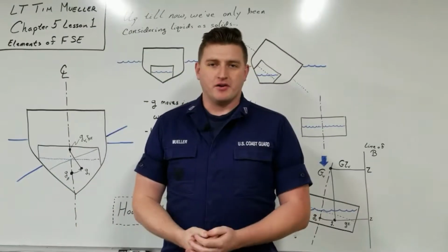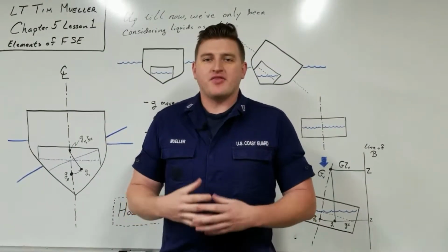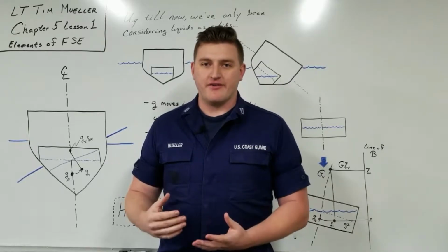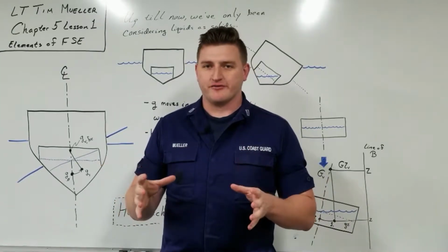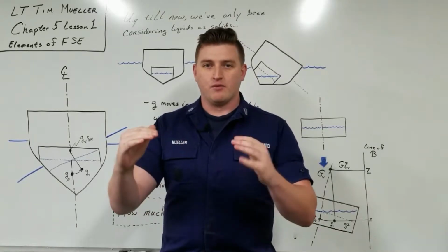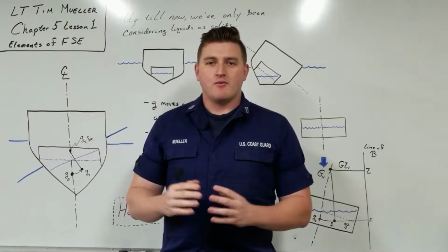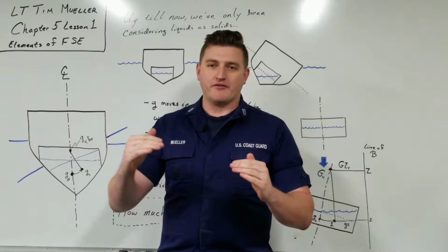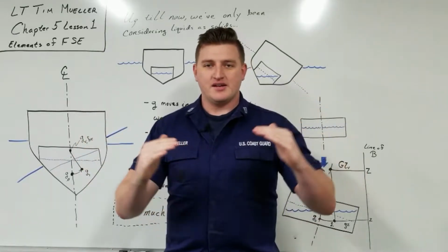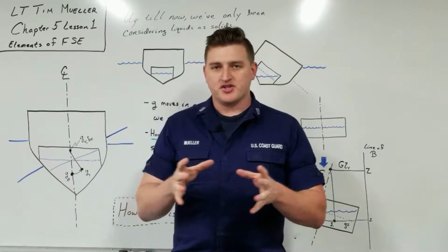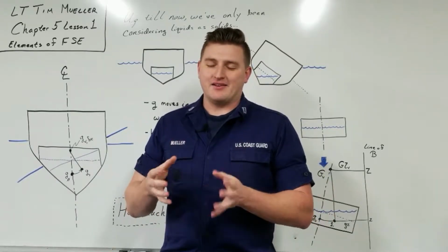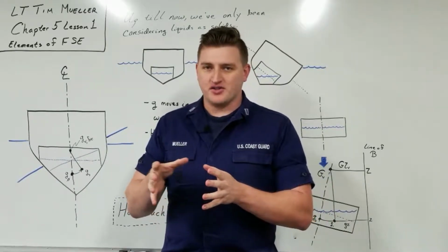Now, when it comes to stability, pretty much every single time we think about stability, we have to think about center of gravity. When we have a ship rocking back and forth, if we go into that inertial frame where we keep the ship still and the waterline moving around the ship, we can kind of think of the water going from one side to the other and it's kind of swinging inside of an arc. This causes horizontal shifts. Now, at different angles, we have different horizontal shifts.